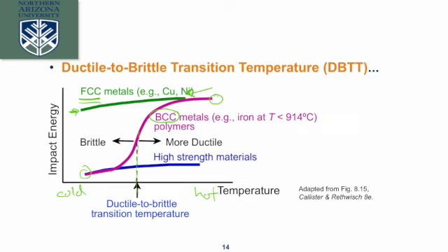They used a material that had nice impact energy and strength at room temperature or normal water temperatures, but it wasn't tested at very cold temperatures like 20 degrees Fahrenheit or below 0 degrees Celsius, where the water can still be liquid because of the high salt content. The metal transitioned, became much more brittle, so an impact from energy from a wave or from an iceberg or whatever, just the weight of the ship itself pushing down on it could cause it to fracture.